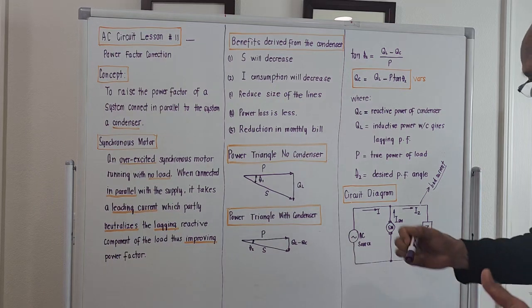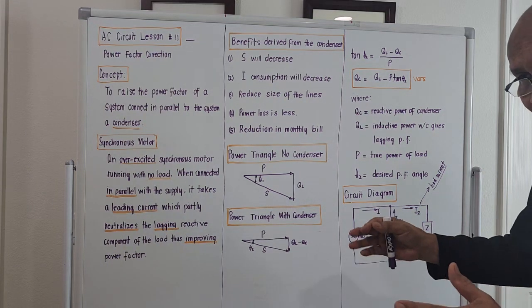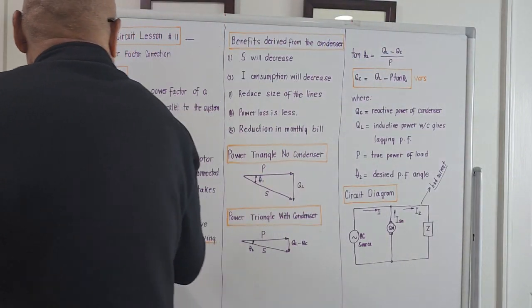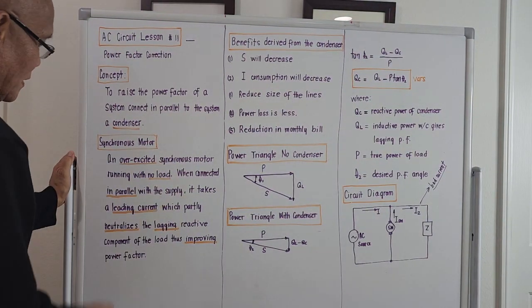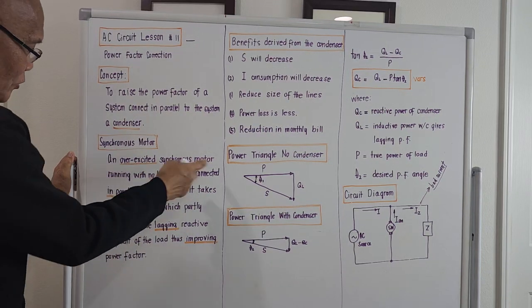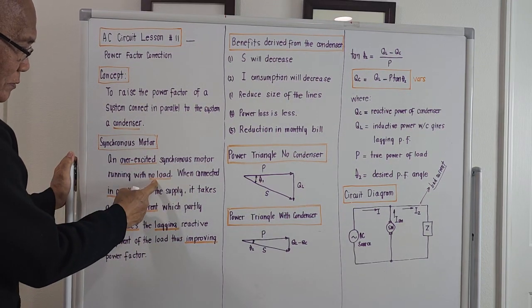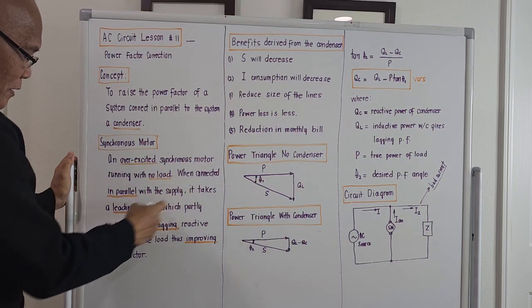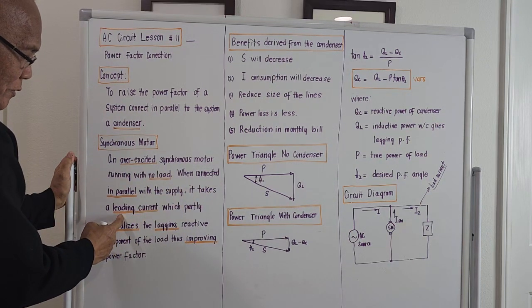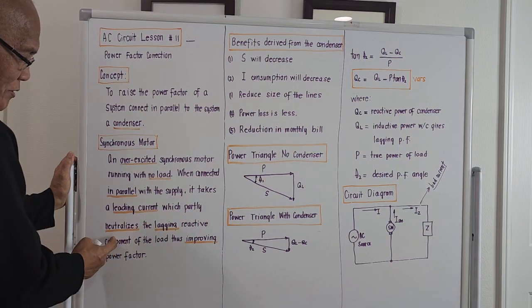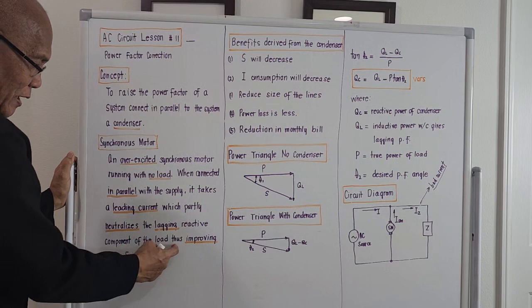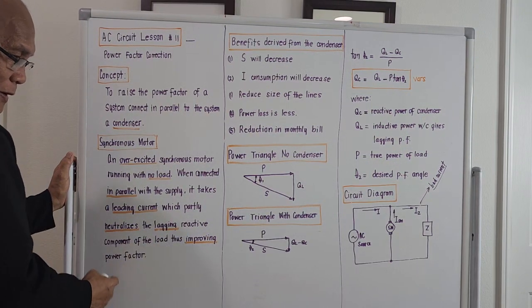Let's try to bring out the concept of the synchronous motor. An overexcited synchronous motor running with no load, when connected in parallel with the supply, takes a leading current which partly neutralizes the lagging reactive component of the load, thus improving power factor.